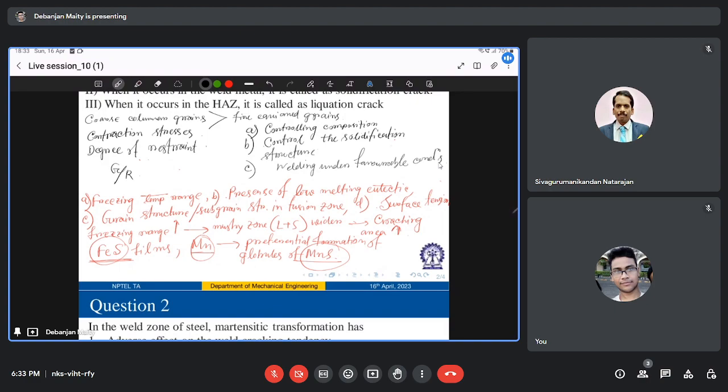Solidification rate and thermal gradient. You can basically play with this G by R ratio and the G times R product. Depending on your cooling rate, those grain structures can vary. Depending on your solidification structure, your metal would be either susceptible to cracking or not, right? So almost without exception, control of the structure means attempting to minimize the grain size, correct?